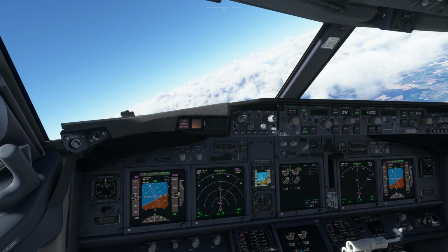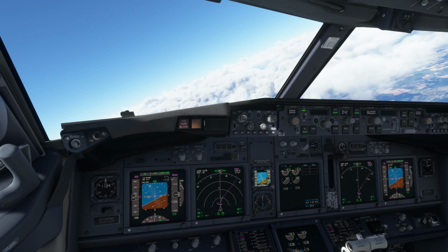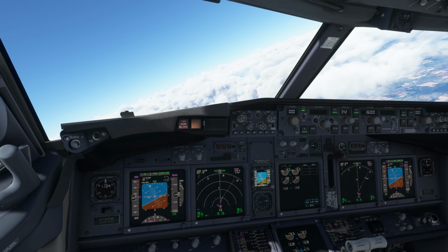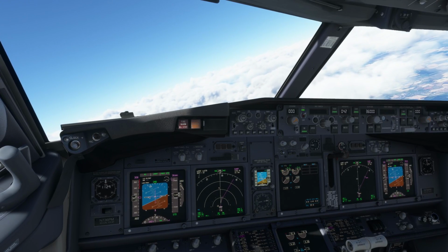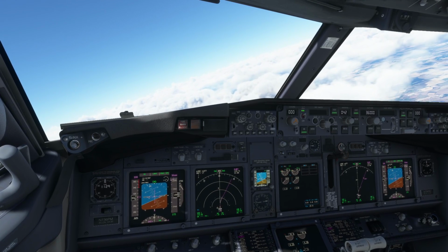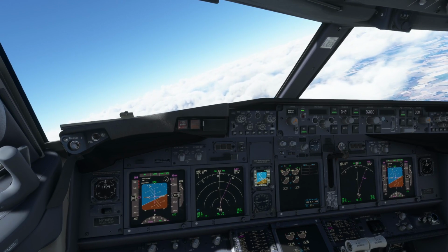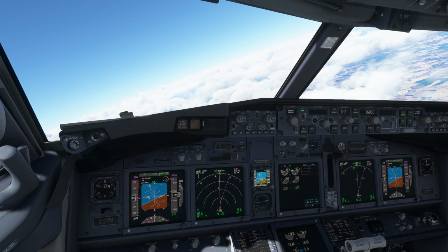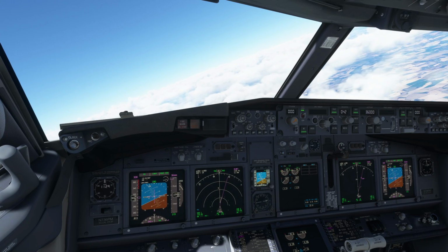Okay, I'm just coming back for a few moments. I've just done a little bit of reading. The reason I couldn't find the transition altitude on the operational flight plan is because it's not on there. It only appears on the charts. I suspected it might be in the operational flight plan, but I was mistaken. So anyway, there you go. The transition altitude you'll have to look up from charts, but take it as read that most of the UK is 6,000 feet.